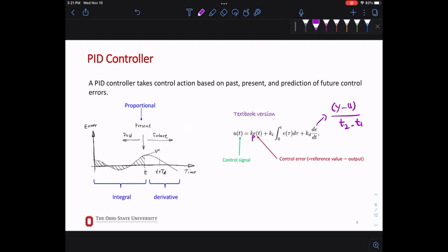Now, we usually go P. If P didn't work, we go PD. If not, we use PI or PID. Whenever you add the integral term, you will see lots of oscillation in your system. Whenever you have lots of oscillation, you can add KD as a damping type of controller. It will damp your oscillation. If you have overshoot, you can use KP to bring that maximum down.